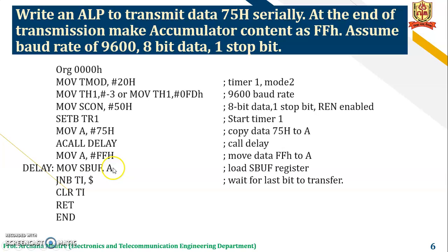In the delay program, the accumulator content is moved to the SBUF register, and the status of the TI bit is checked. When the transmit bit is set, clear that bit and return to the main program. In the main program, lastly we have to make the accumulator content FFH. So the value FFH should be moved to the accumulator.